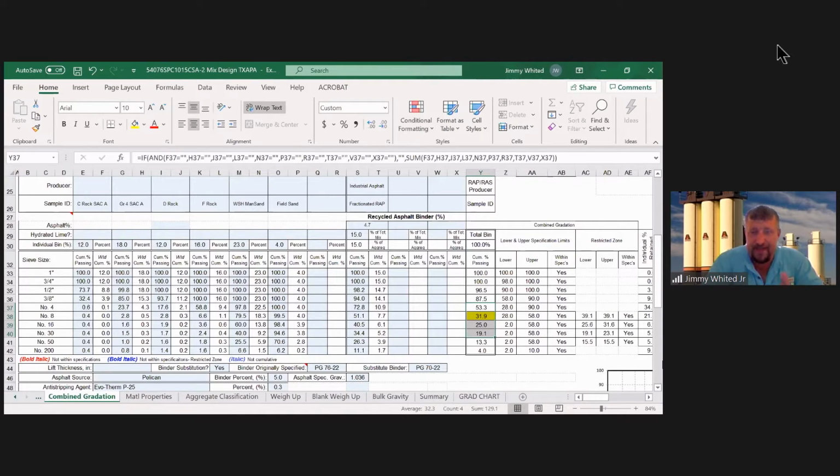We watch these moistures and tie them back, because on the same sheet you have your stockpile gradations, your moistures, and your hot mix samples themselves with densities, gradations, everything. When you start tying these numbers in, they all reflect each other. You get a heavy rain, we will not crank up a plant if our stockpile moistures are above 10%. If you crank up with stockpile moistures above 10%, you're asking for trouble.